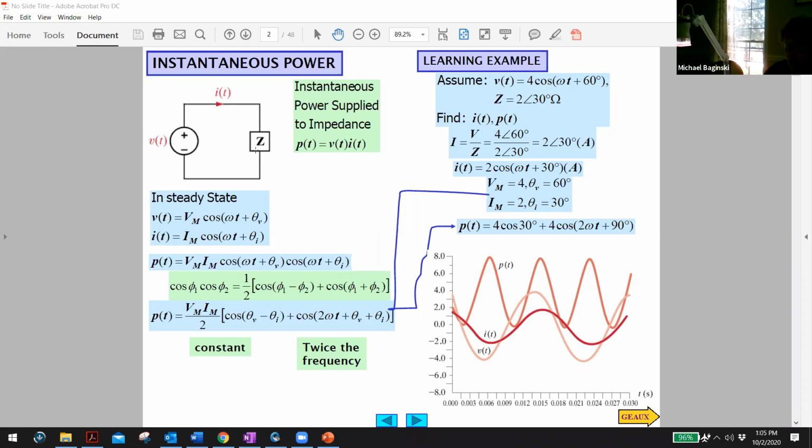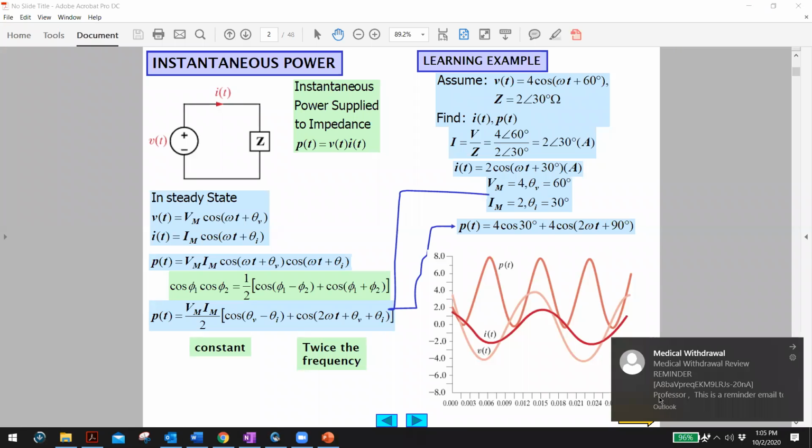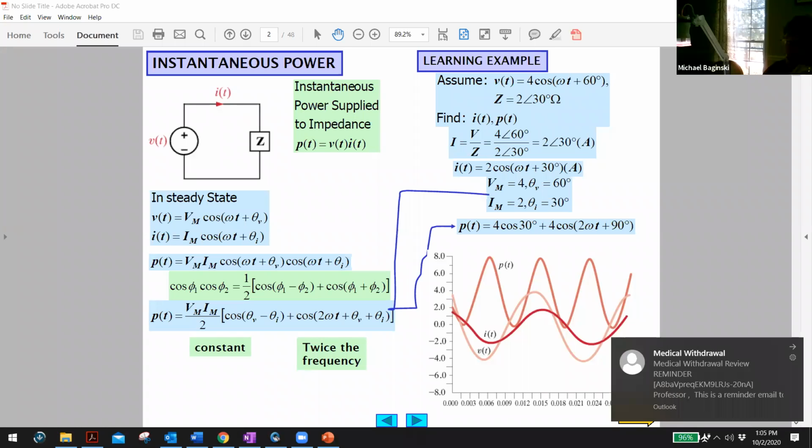Think about this, right? Suppose there's a voltage plus to minus, but current's leaving. Then effectively, wouldn't we have a negative power because the current would be negative, whatever it is, times a positive V. Do you all follow me? Just, you with me on this? Now, what that means is that the concept of negative power is actually a supply.